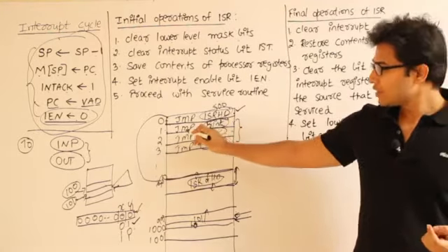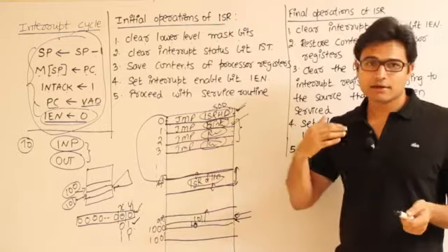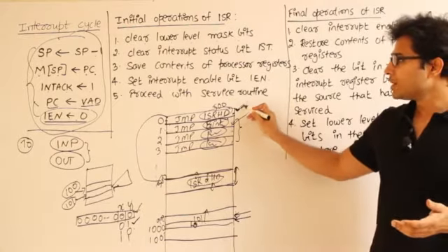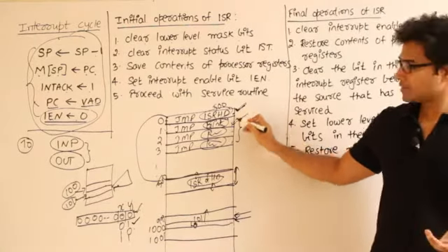It will not hurt the low speed device at all, because the high speed device requires only a small amount of time, but the low speed device will require a lot of time. You can think of it this way: maybe this one takes microseconds, this one takes milliseconds. That is why we always let the high speed device interrupt the low speed device, and that can be done by using these interrupt service bits.